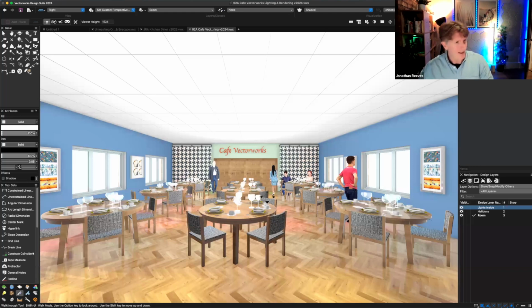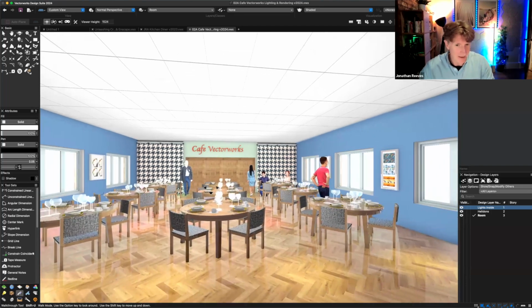And I don't know whether you're aware of this, but in Vectorworks, there was a limit on shadows. That was removed last year. And there was a limit on lighting, and that's been removed this year, or the other way around. There used to be 8 shadows and 8 lights. That was the maximum. So if you've ever looked at rendering in Vectorworks before and it didn't look as good as you wanted it to, that could have been the reason. But with no limit on shadows and lighting now, and things like these environmental reflections, I personally think the rendering for actual CAD software is absolutely brilliant.